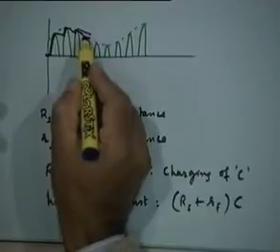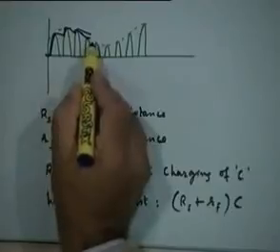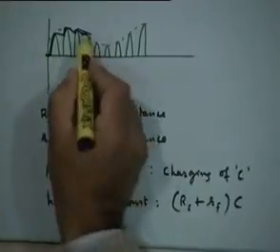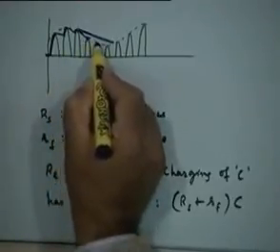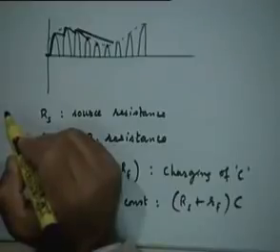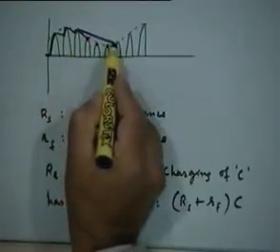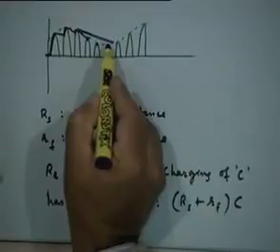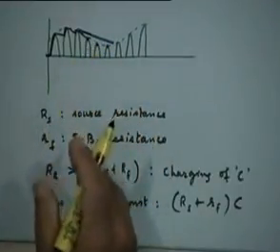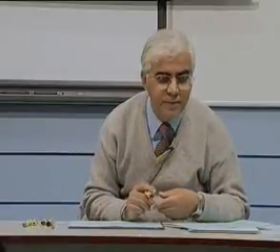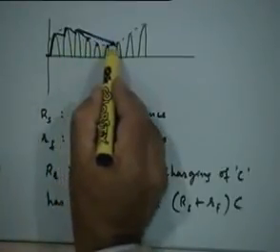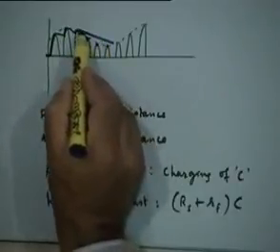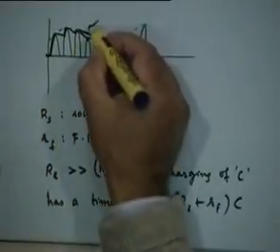Is that good or is that bad? It is bad because you are not following the envelope, right? So this would lead to a kind of clipping. You would miss all these variations in between, right? So while this discharge time constant should be slow, it should not be so slow that it does not follow the fast fluctuations that might take place in the envelope itself, right? This envelope fluctuation here is much faster than the rate of discharge of the capacitor, and therefore there is a kind of distortion that will come up in the envelope which we call the clipping distortion.